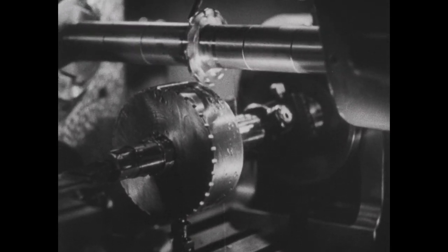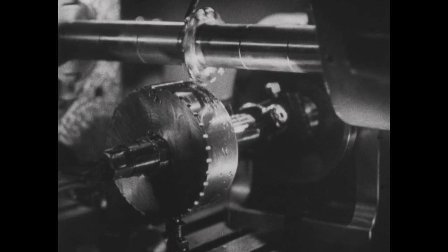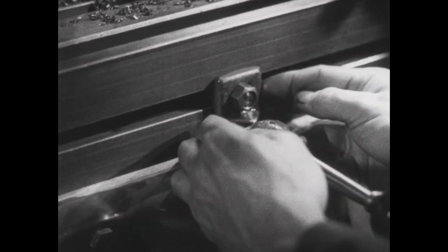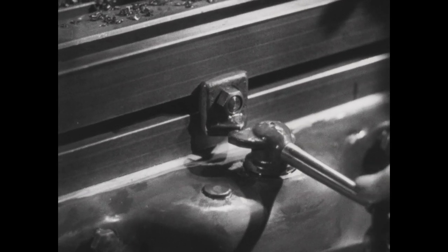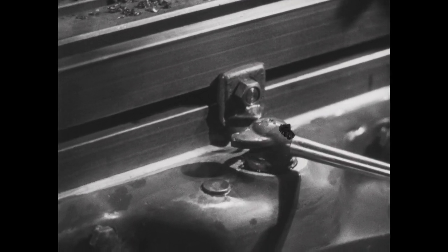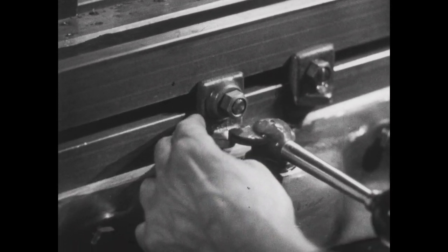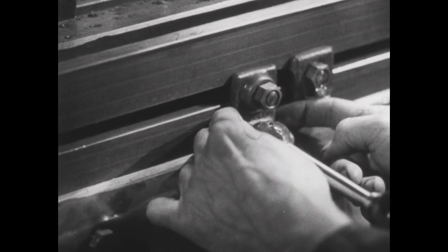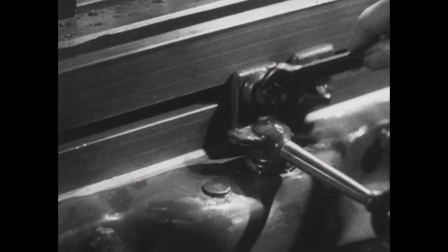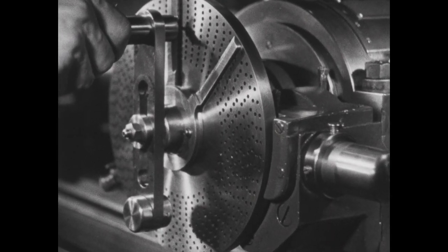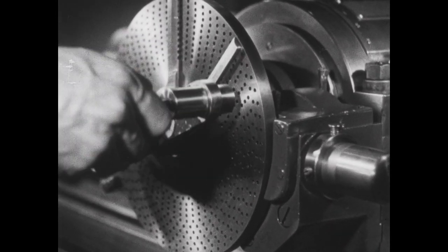When the first roughing cut is completed, the operator stops the cutter. With the table in this position, an automatic table stop is located to prevent the indexing head from running into the cutter on the subsequent cuts. Another stop is also located to save time when the work is moved back to the starting position for each new cut. Now, the operator is ready to make the balance of the roughing cuts around the gear blank.